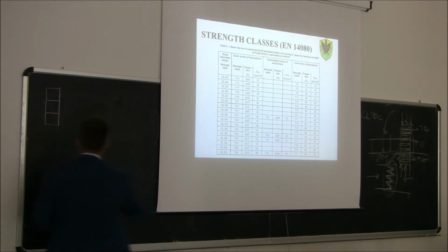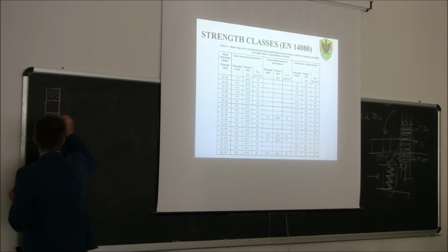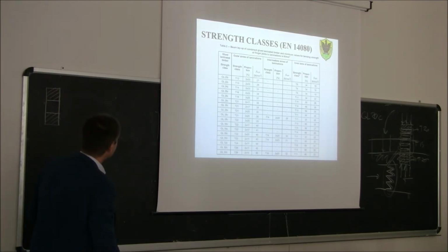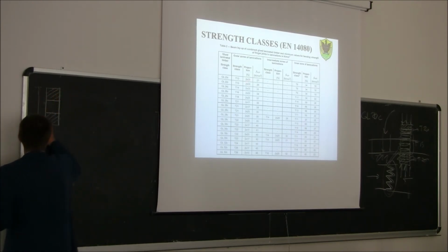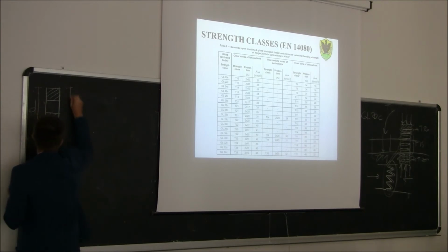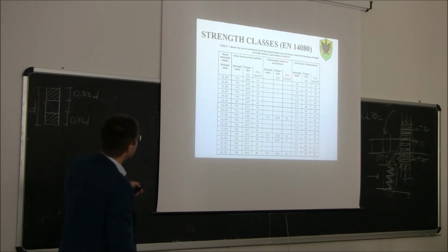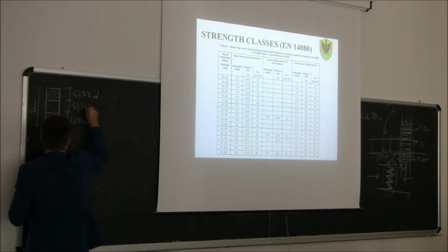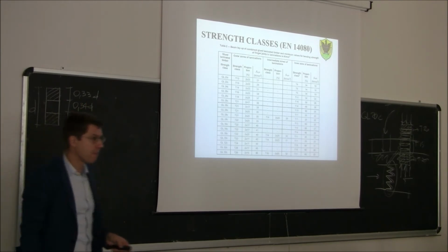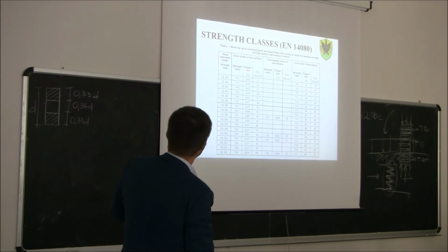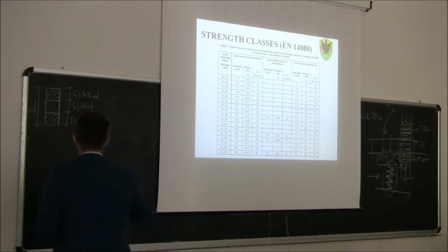Outer zone of lamination. So the outer zones of lamination are those shaped ones. Proportion 2 times 33%. So if this is, let's say, D, this should be 0.33 D, and this should be 0.33 D. Inner zone of lamination, 34%. So this should be 0.34 D. Okay? Then, strain classes in the outer zone of lamination here,